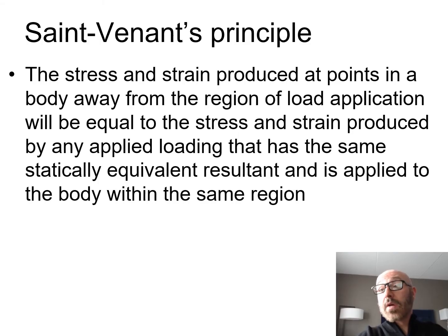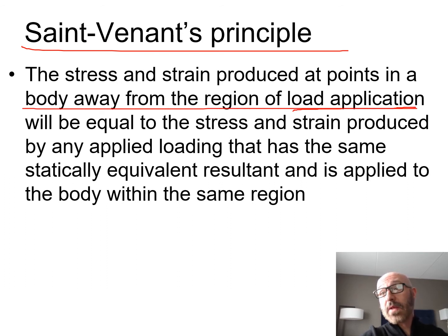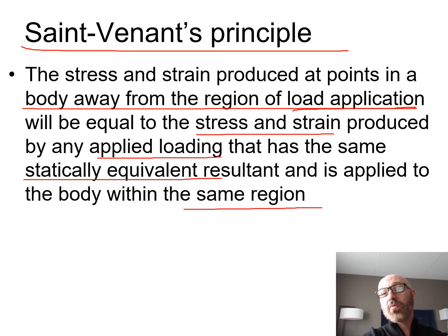So next I want to talk about St. Venant's principle. What this is primarily saying is that the stress and strain produced at points in a body away from the region of the load application are going to be equal to the stress and strain produced by any applied loading that has the same statically equivalent result, and is applied to the body within that same region.